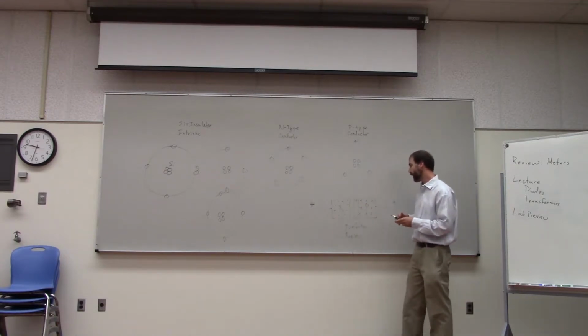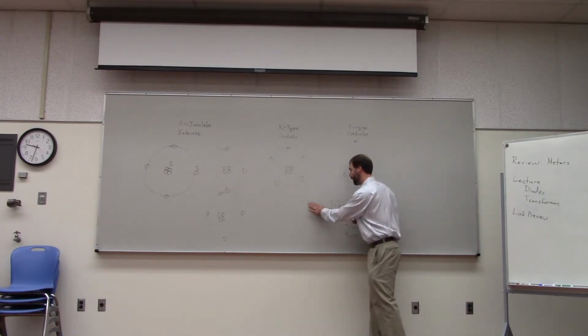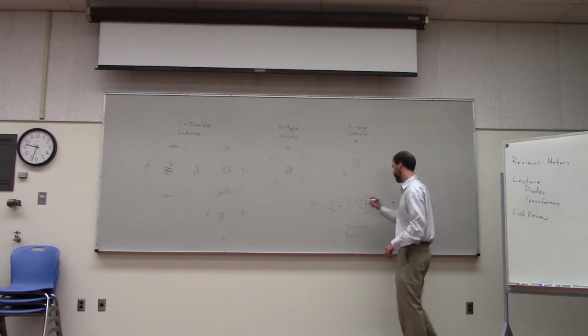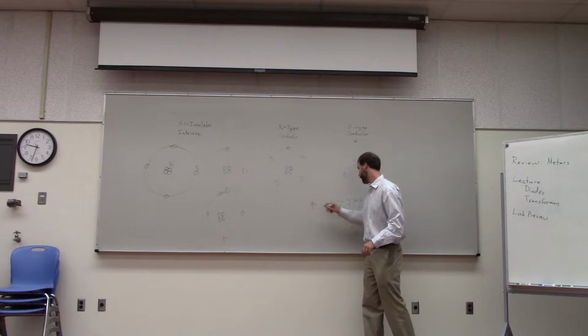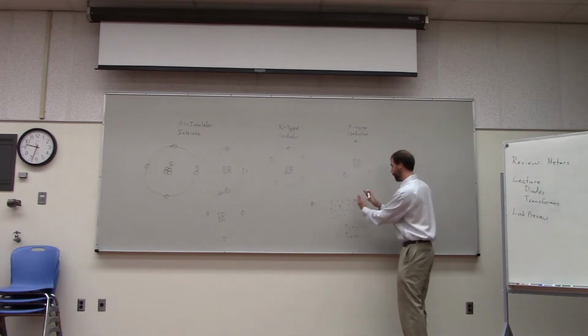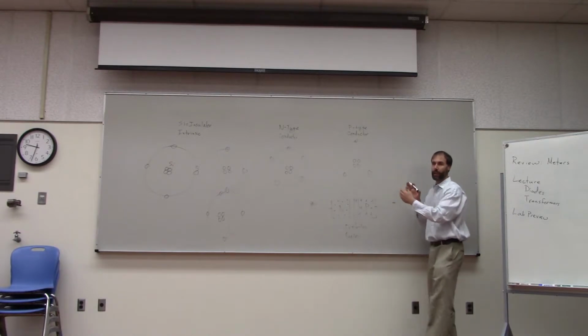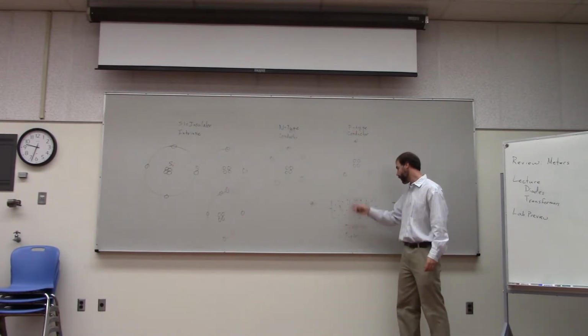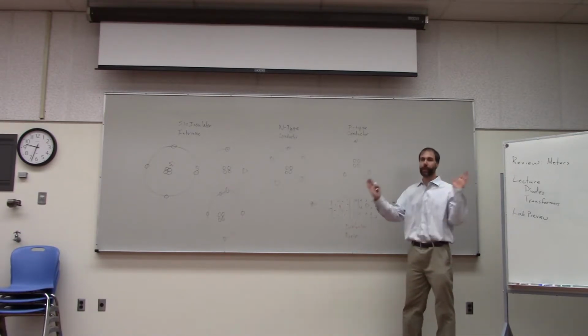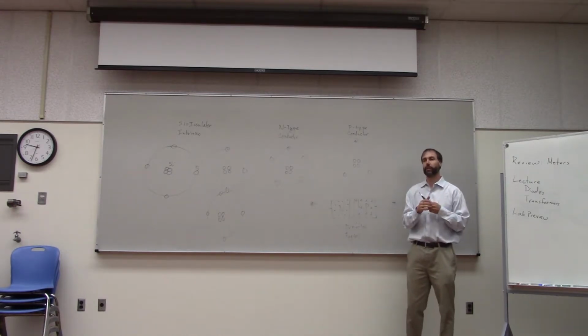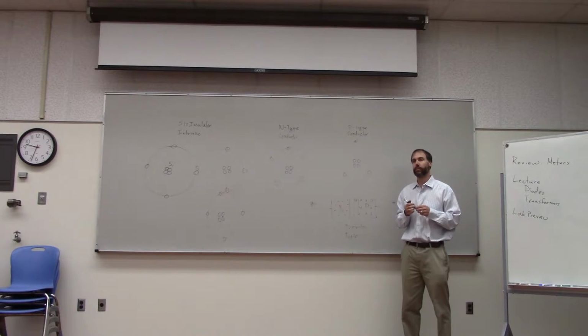If you were to apply the voltage in the opposite direction, negative voltage over here and a positive voltage over here, then you're sort of pulling the depletion region apart. You're making it bigger, so you're creating more of an insulator in the middle. That's why it does not conduct in the opposite direction. It essentially acts close to the way a capacitor acts, right?